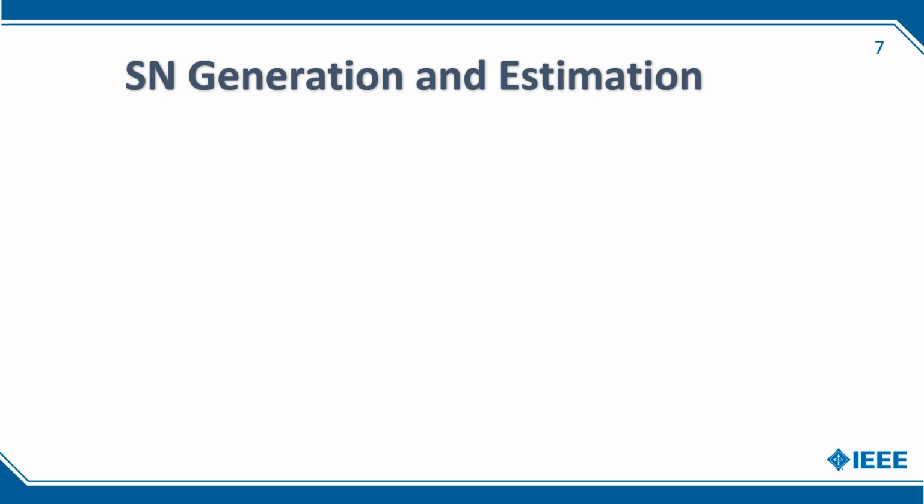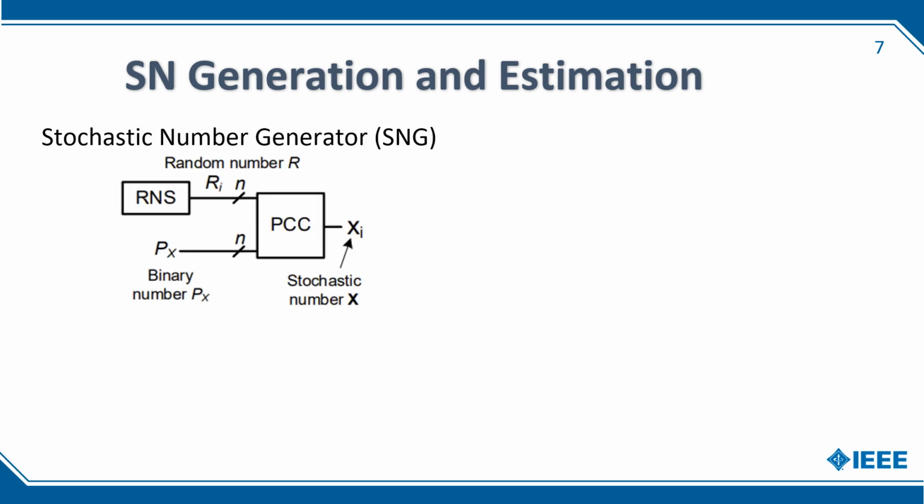Unfortunately, efficiently achieving the desired level of correlation between bit streams is often challenging, and in practice too much or too little correlation is a main source of error in SC. Our paper focuses on the correlation and error implications of the stochastic number generator, SNG, component.